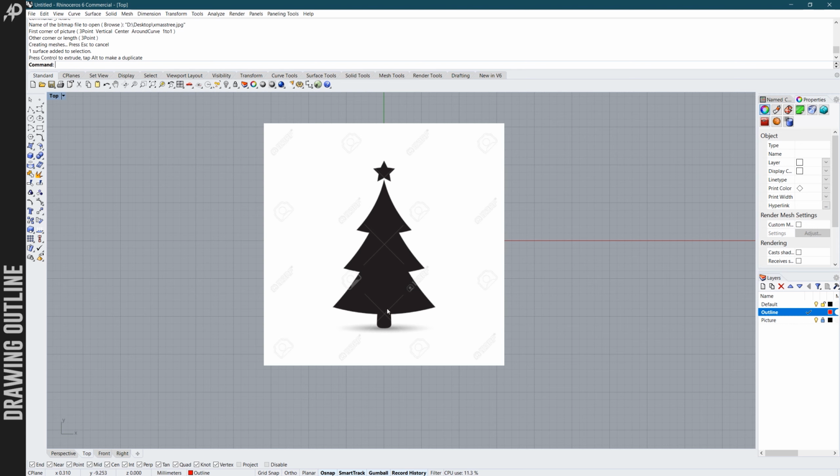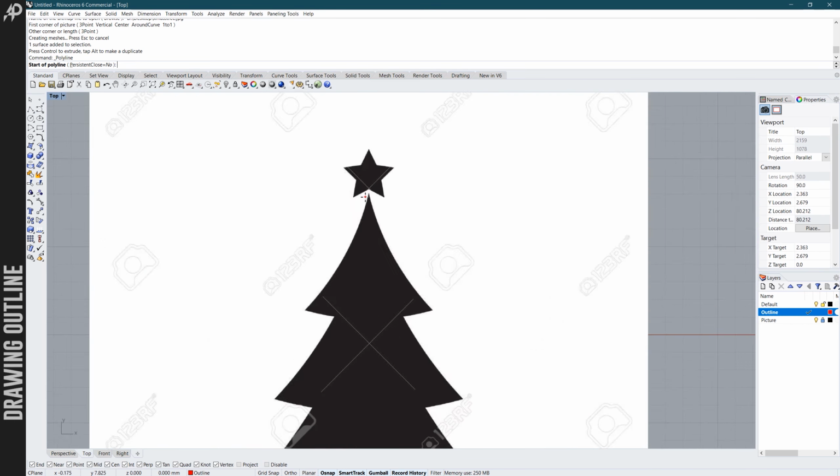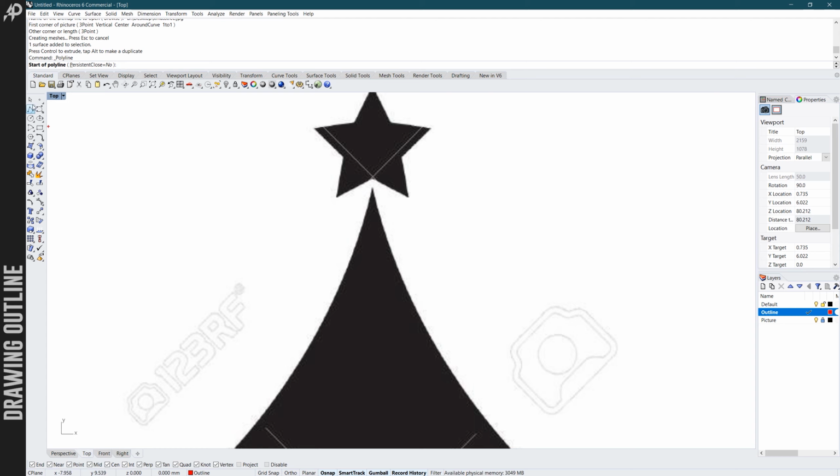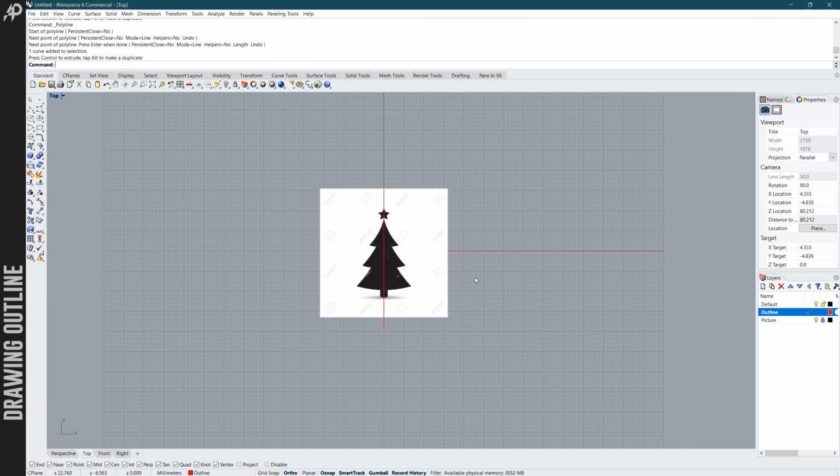What I see at first sight is that my object is symmetrical. So we will just draw one half and then mirror it to the other side. So first I will draw my axis of symmetry. I have just chosen the polyline command here. I will click somewhere near the middle. You can either use Smart Snap to create a perpendicular line, or you can turn on the ortho function that will only allow you to draw perpendicular, and you do it by pressing F8 on your keyboard, or just press ortho here. Now I've made my perpendicular line, I move it a little.